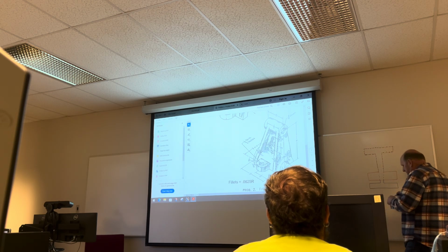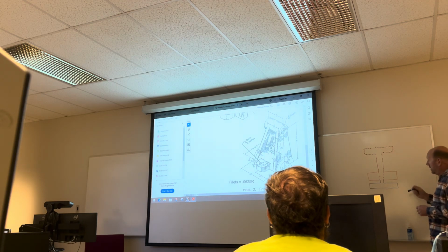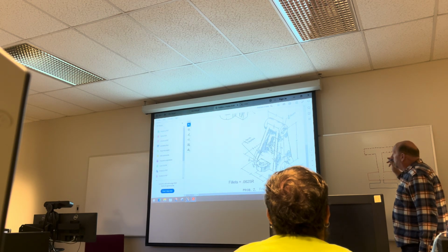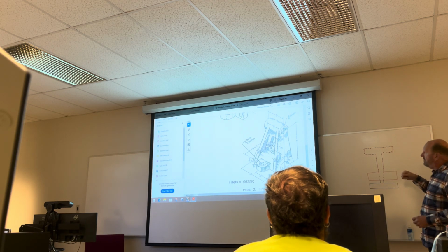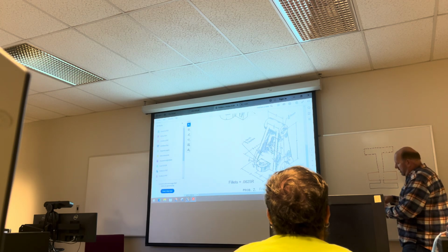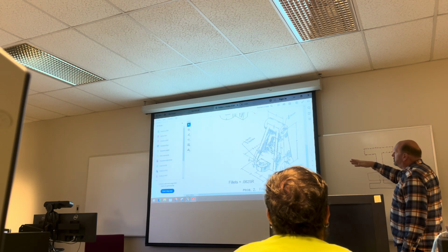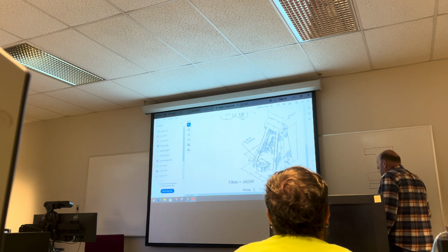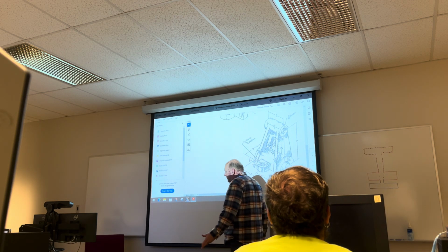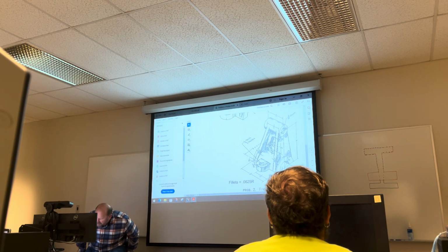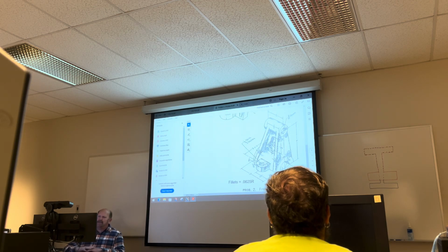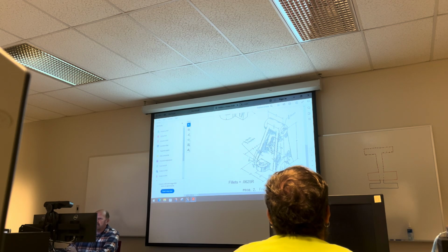And obviously, if you're looking at both sketches from the plan view, you won't see anything. You'll see these two sitting on top of each other. Then when you connect those two together, it stretches them out, and it also creates the shape that you need for this part. There's a little bit of development work up front, but trying to do this by using pads is very difficult. You have to put a lot of planes on the part. You also have to do a little bit of math to figure out exactly where the part's gonna be.